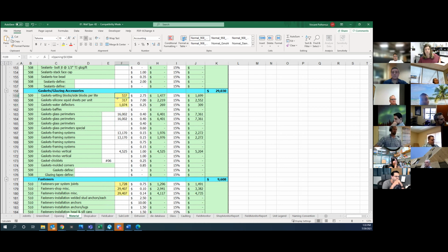This is my total number of lights, my total number of units, my total number of lights times 2 to get these things. But then the estimators were going and calculating all these numbers, glass perimeters, everything else. Miranda had done a fantastic job researching gaskets and looking for patterns, and came up with the fact that the reality is if you take your glass perimeters and do 12 cents a perimeter inch, and then we add, I think it's 5% overage, it covers us on everything without getting into heavy detail on the types of gaskets that you need to use.